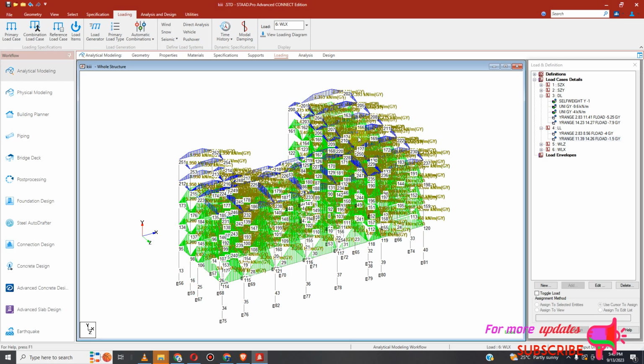The way a slab acts, it's like connecting several nodes together, so that their motion depends on one node. So if one node moves, the rest of them are going to move, because the slab is stiff, it's solid. So in this model, that principle is lacking. That's why my analysis is taking too long, because there's an error.